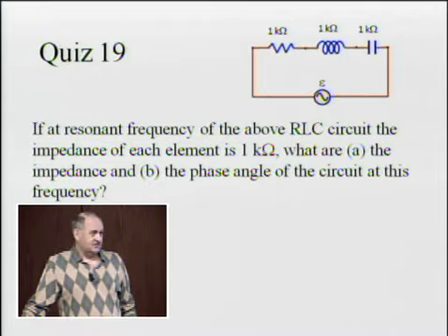And if the elements are connected in series, the complex impedance of the combination of inductor and capacitor would be i omega L plus 1 over i omega C. If I factor out i, I will have omega L, which is the impedance of the inductor, minus 1 over omega C, which is the impedance of the capacitor, and if these two impedances are equal, they add up to 0.